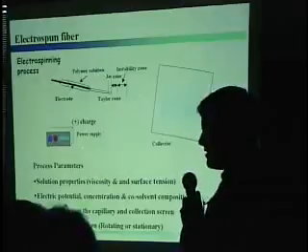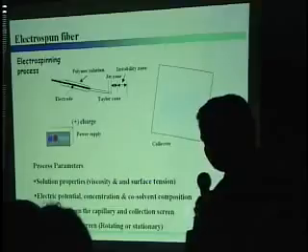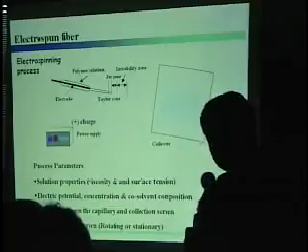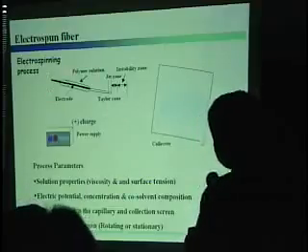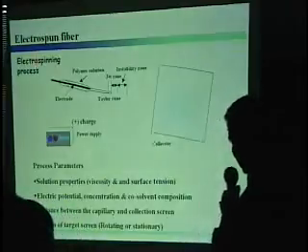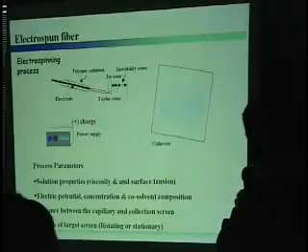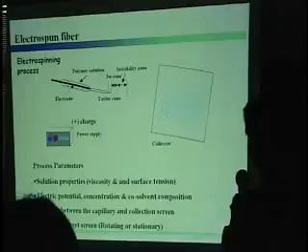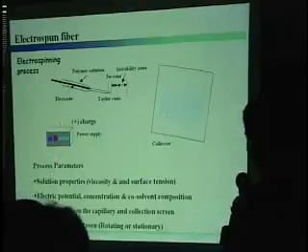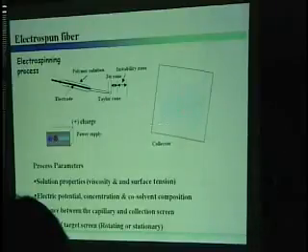is the simple electrospinning process. Just before this presentation, we discussed this type of electrospinning process and its physics. You may already be familiar, and it is very well known. The polymer solution is kept here, and using the electric field, the polymer is ejected from the capillary tip as fiber, and these are some factors which can affect the morphology and diameter of the fiber collected here.